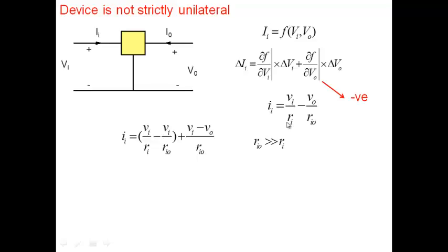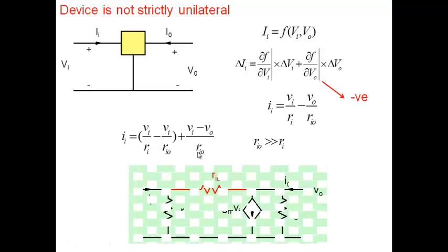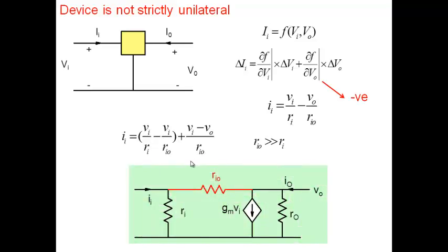the original model. But if you would like to build a next order approximation, then we can modify our model to this here. Note that the input current that I've written here is made up of two terms, this plus this. The second term says Vi minus V0 by Ri0. How do I represent it? It is represented by an element here. This is Vi, this is V0 here. So Vi minus V0 divided by Ri0 is this current here. So it represents this.